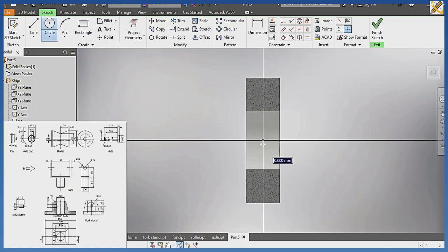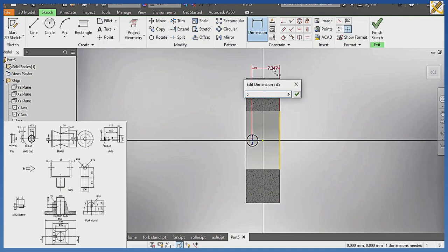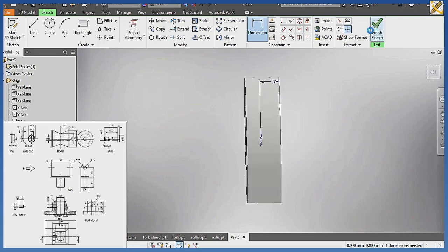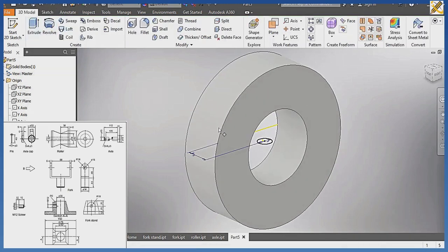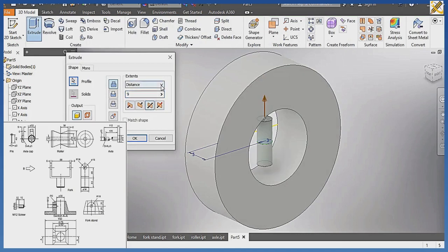I'm having that right there, so picking my circle right about now. So from the center right here, I'm drawing a circle of, sorry, not from the center, escape. Picking my circle, but right on this area here beside the center point, I'm drawing a circle of diameter 3, enter. Okay, then I'm going to pick my dimension from the center of this circle towards the bottom right here to be mark of what, mark of 5, then what, enter. Then what, I'm going to finish my sketch. Then I'm going to click on what, extrude. I'm going to click on symmetric, distance to the what, all. Then I'm going to pick what, cut, in that order.